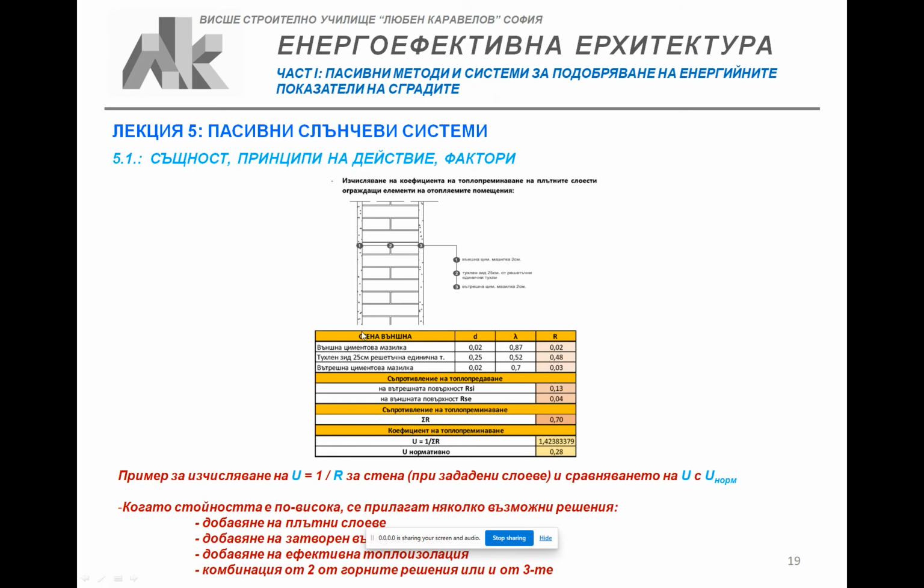Usually, this is the way to calculate a building solid element coefficient. A schema of the layers of the element, some explanation, the thickness in meters and the specific coefficient of each single material, the final result, and also adding two air layers adjacent to the wall. They are centimeter thick, and one is next to the inside surface of the wall, and the other is next to the outer surface of the wall. They are not calculated; they are just added.